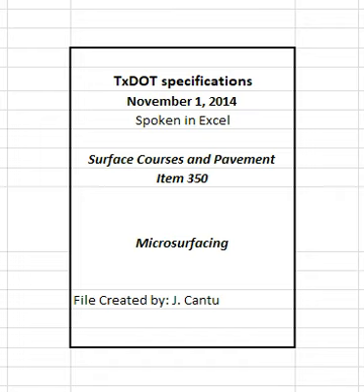Prevent loss of material from the spreader box by maintaining contact between the front seal and the road surface. Adjust the rear seal to provide the desired spread. Adjust the secondary strike off to provide the desired surface texture. Clean strike off regularly to prevent buildup from occurring.